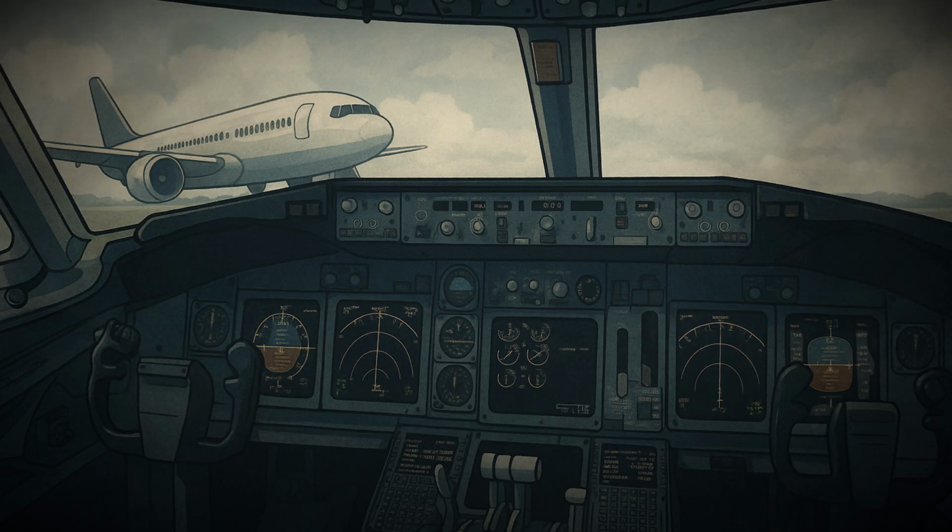The importance of drag in aviation cannot be overstated, because drag directly influences fuel consumption, range, and performance. The more drag an airplane experiences, the more thrust is required to overcome it. And since thrust comes from fuel-burning engines, higher drag means higher fuel costs and greater environmental impact. Reducing drag has therefore been a priority for decades of aviation research.